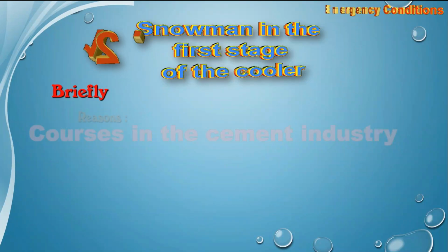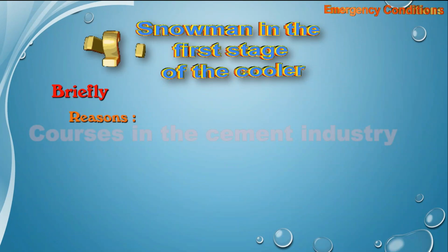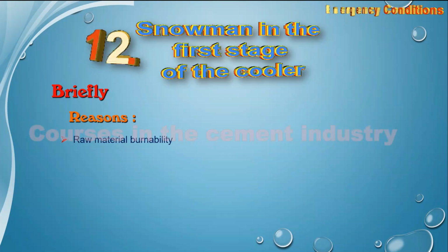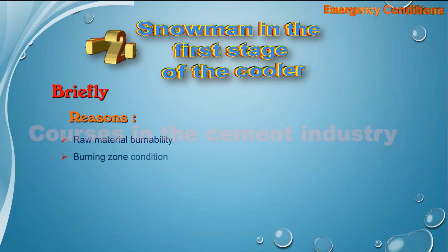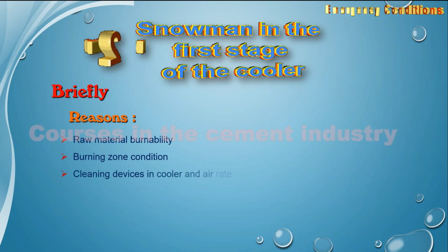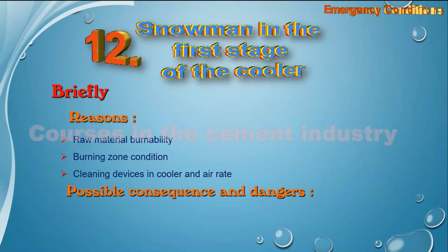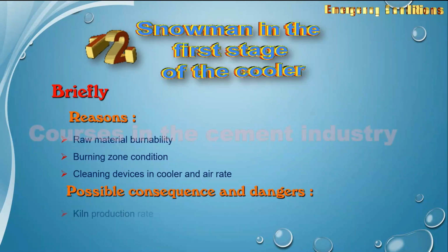Briefly. Reasons. 1. Raw material burnability. 2. Burning zone condition. 3. Cleaning devices in the cooler and air rate. Possible consequences and dangers: kiln production rate.